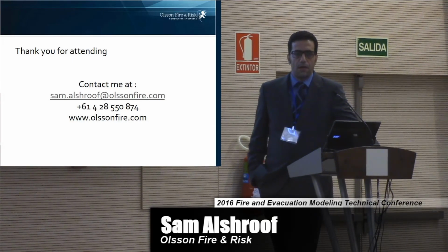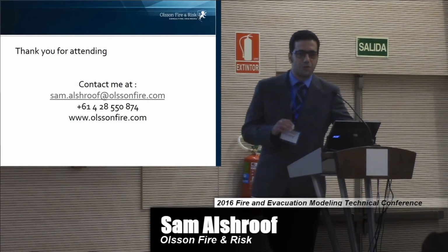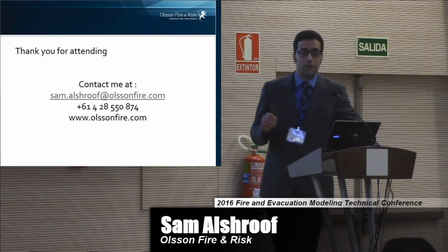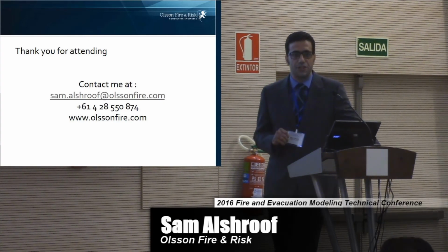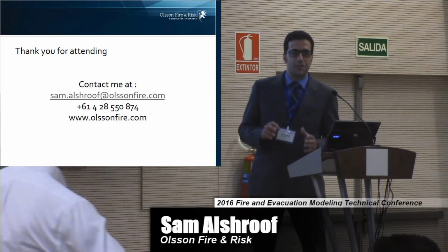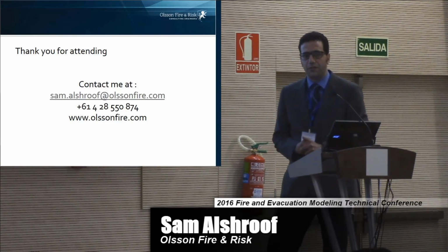Did you consider to simplify the problem? Because I know that FDS is not that great at solving any wall boundary condition. I did put my walls as slip wall boundary conditions, so I don't have that issue. I try to reduce the parameters as much as I can, just to make sure that I'm trying to come up with a solid conclusion by the end of the day.